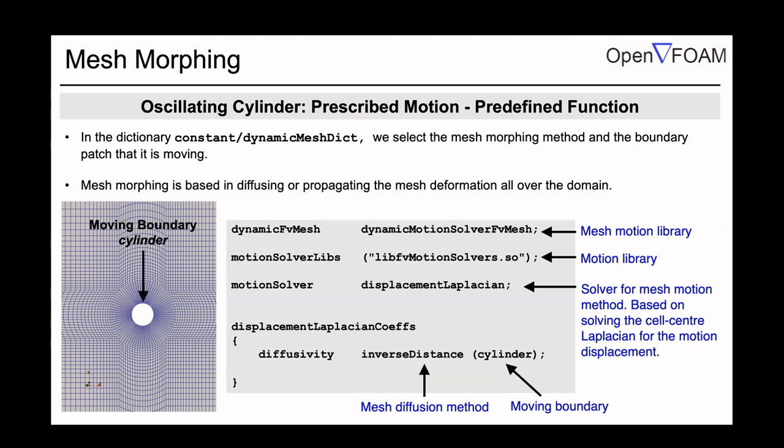One is you can define or use the available functional form of the motion, such as sine omega t or cosine motion or some ramp motion, which are very basic and can be defined through a closed form trajectory. You have a closed form equation for that, so you can write a function, use it, and use the appropriate mesh motion library, coming to this in a while. So that is one way.